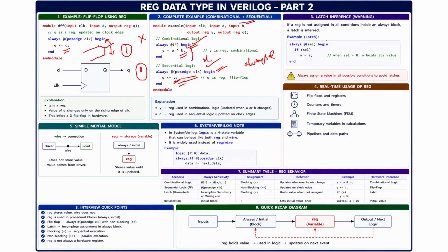So then latches, we can use the select lines or input sensitivity list. Okay, so a latch always uses an always @ block, and then we have a sensitivity list, A or B or C. In this way we can write the sensitivity list. See here, I am designing a multiplexer based on the select line. Every time the select line changes, I am getting some value. So just a 2 by 1 mux you are designing.